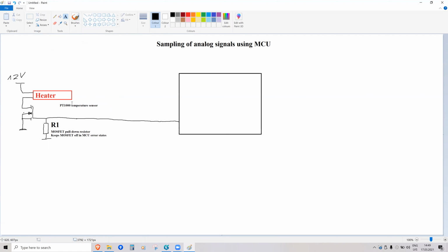It means that its resistance is 1000 ohms at room temperature, 25 degrees. And if it gets hotter, it's made out of metal. Hotter metal has higher resistivity, and at lower temperature, it has lower resistance. So, its temperature changes the resistance. So I'll draw it with some thick line.